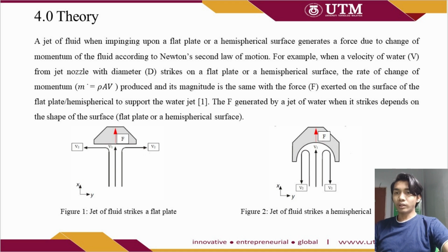For example, when water with a velocity from a jet nozzle with a diameter strikes a flat plate or hemispherical surface, the rate of change of momentum produced has the same magnitude as the force exerted on the surface of the flat plate or hemispherical surface to support the water jet. The force F generated by a jet of water when it strikes depends on the shape of the surface.